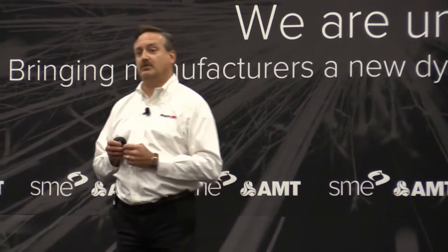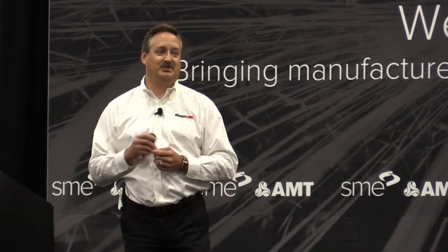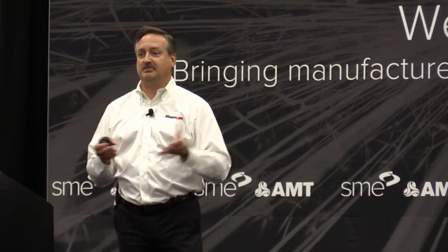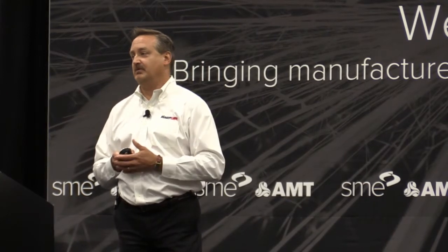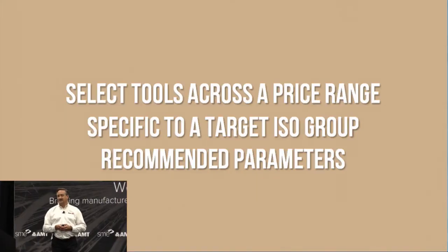And then the third one, we were going to go with the cutting tool vendors' recommended parameters, okay? Now that's important to remember because the cutting tool vendors, they're going to specify what surface feed you're going to be running that particular tool at. They're going to specify what feed per tooth you're going to be using, and we went with it, okay? They're supposed to know their tools. We're going to run them.